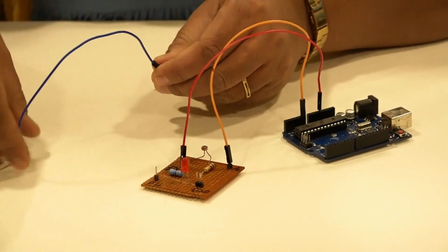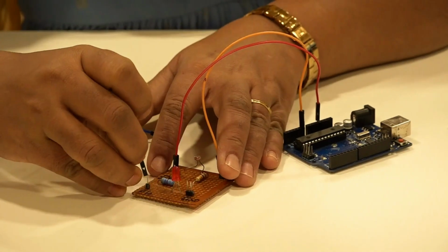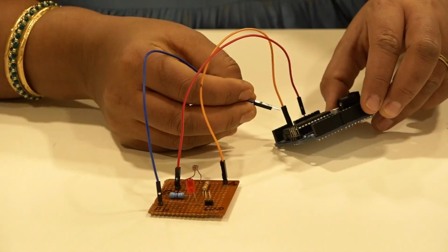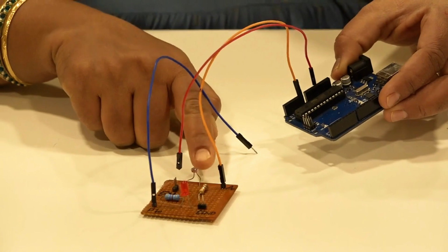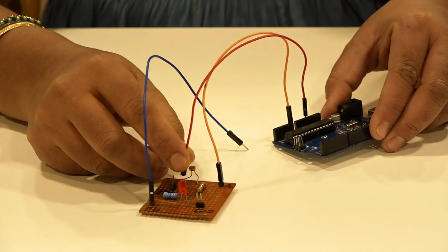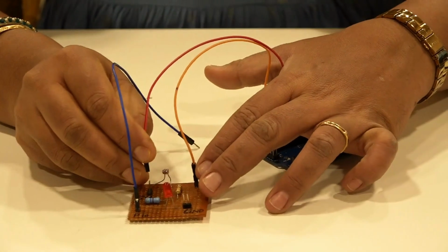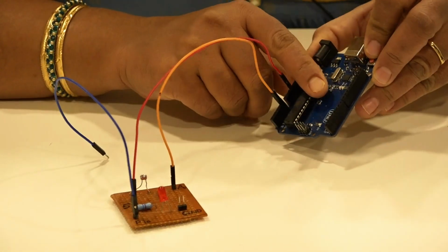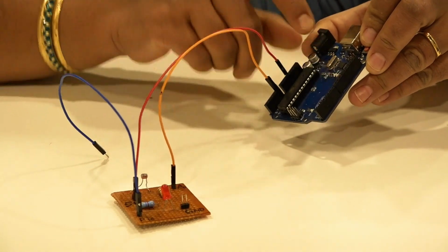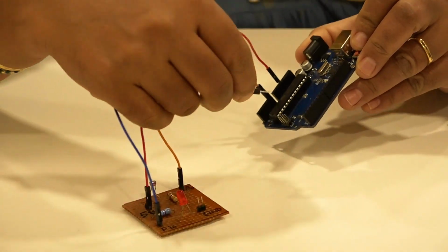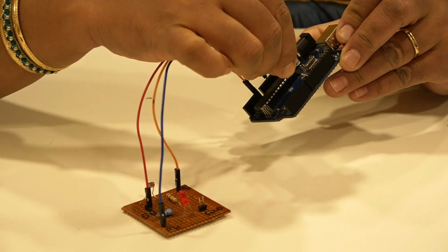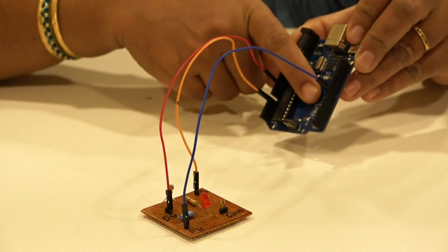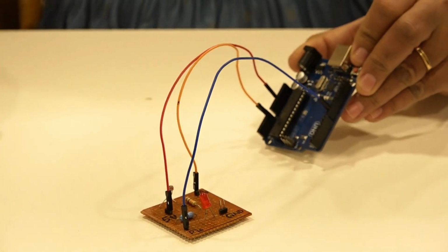Next you are connecting the LED connections. LED connections, one is for the digital pin. So this also again depends on what pin number you are writing in the program. So I have written 9 pin. For this we should choose PWM pins. PWM pins means beside the number in the Arduino board you will see tilde symbols. So here 9, 10, 11 are PWM pins. So I have chosen 9th PWM pin. That's why I am connecting it to 9. LED output I am connecting to 9th pin, digital pin, that is PWM pin.